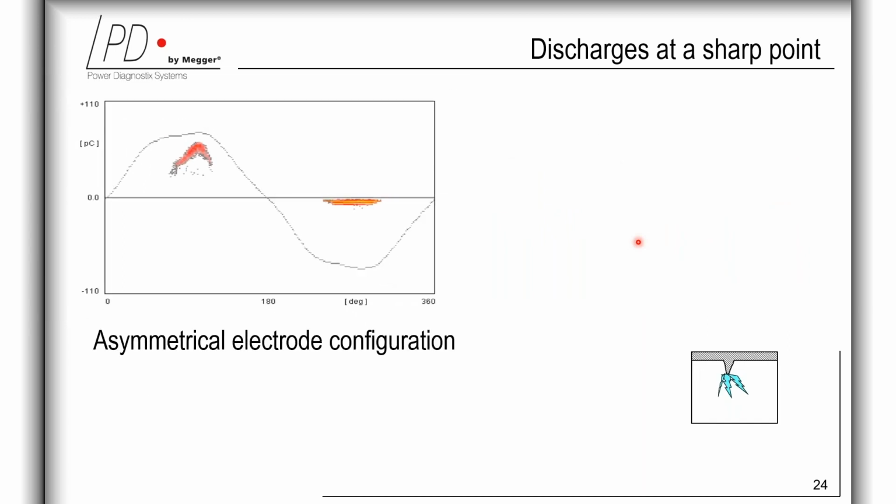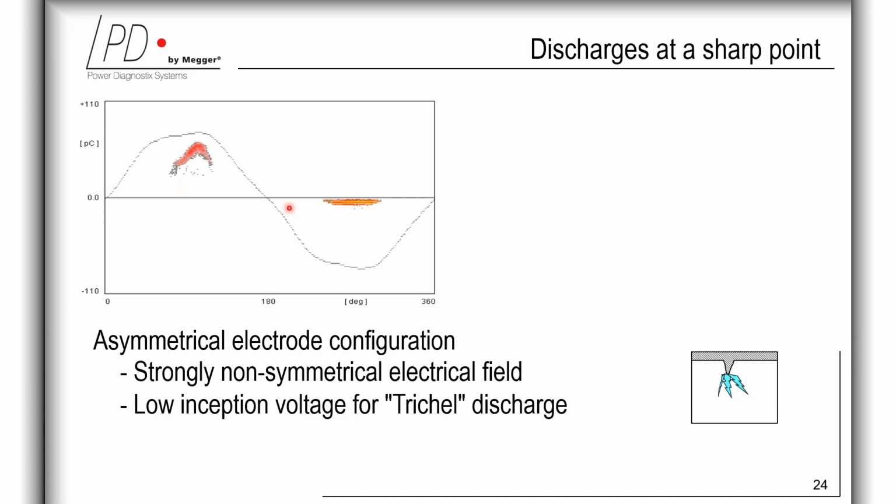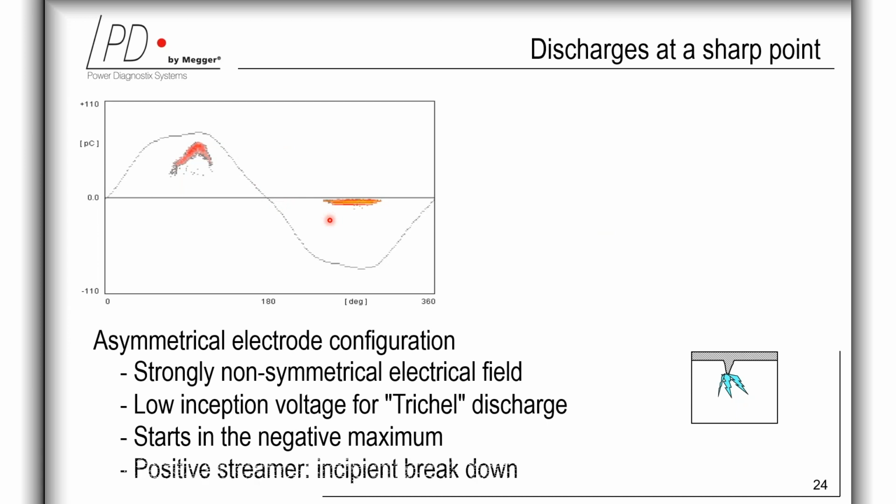So in this slide, we see a partial discharge activity, which is more controlled by the strong asymmetry of the electric field. This is an example of a point-plane discharge, which is a candidate with strong differences to the processes of partial discharge in spherical voids. In case of such a sharp metallic tip, unlimited starting electrons are available.